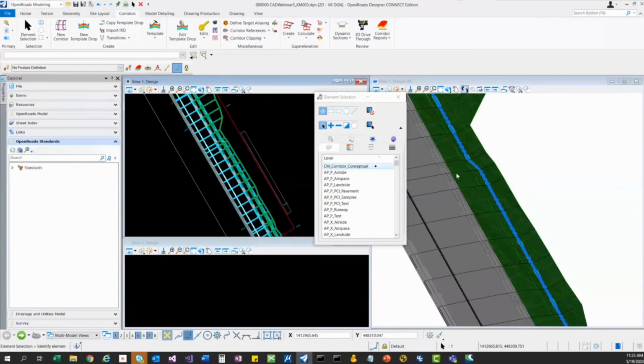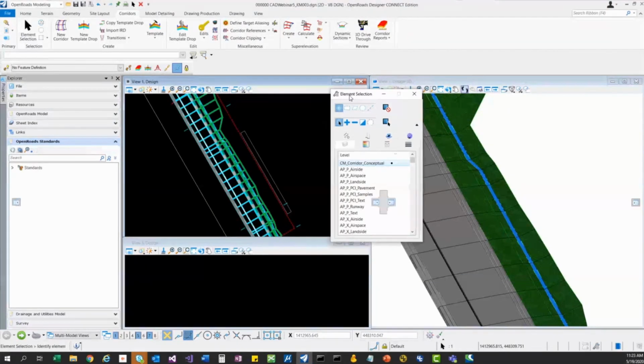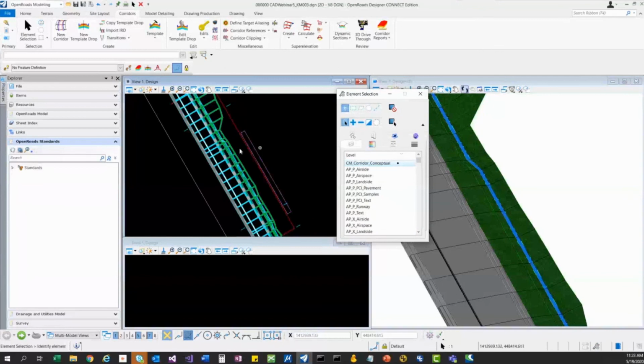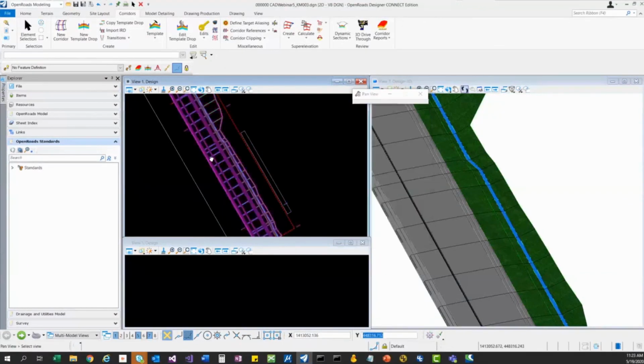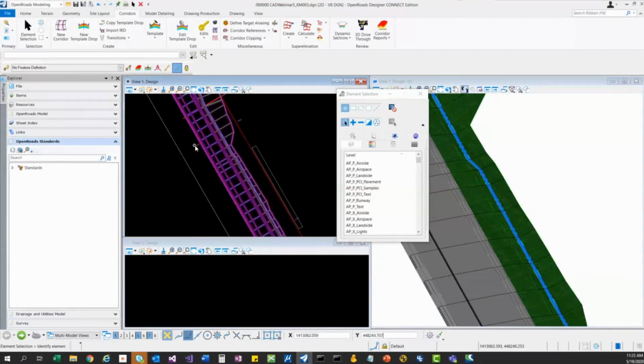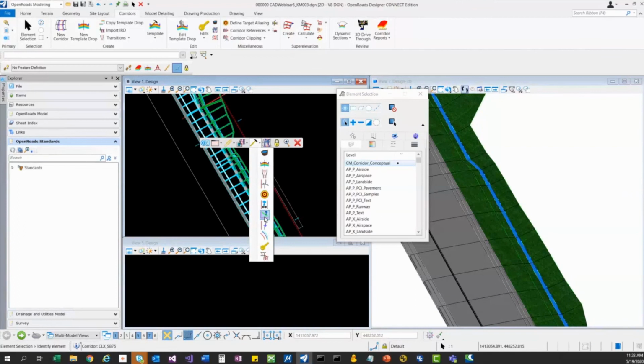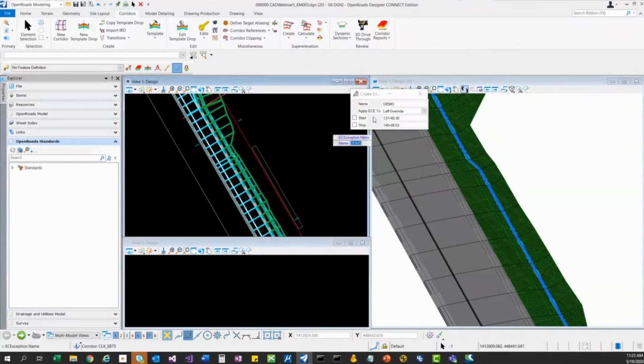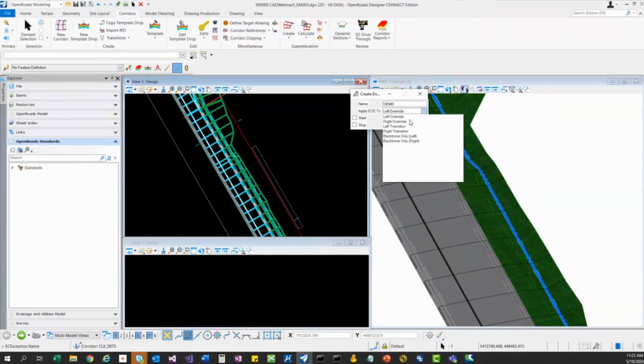There's going to be cases where you go from maybe a ditch to no ditch, and you have fewer points, so that transition didn't really work out well. So that's a good thing to have, a transition condition exception. So I'm going to just add one to show how that works here. If I come in here and add another end condition exception, this time it's going to be a left transition.